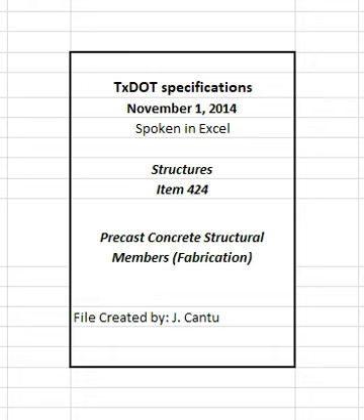Provide certified calibration of each ram before starting stressing operations on the project and every 6 mo thereafter for post-tensioning operations, every 12 mo thereafter for pre-tensioning operations, and as requested by the engineer. The calibration frequency for multiple strand pre-tensioning equipment may be extended to every 24 mo thereafter if an approved master gauge system monitors it. The master gauge must check this equipment when suspect results occur and at least every 6 mo. Calibrate the master gauge per the manufacturer's recommendations and at least every 12 mo.